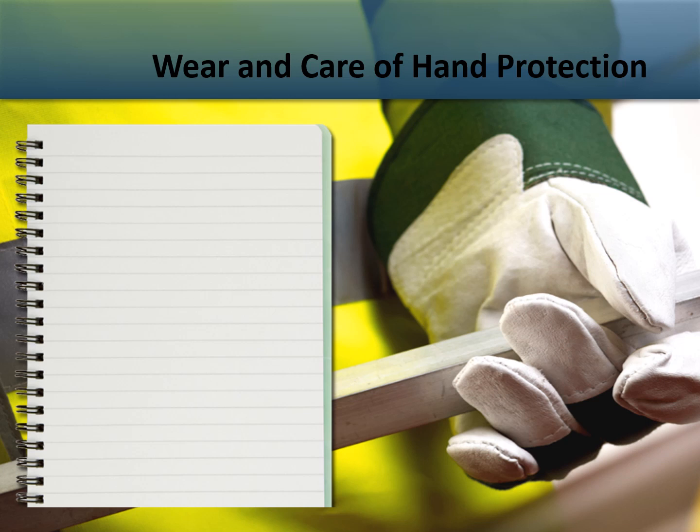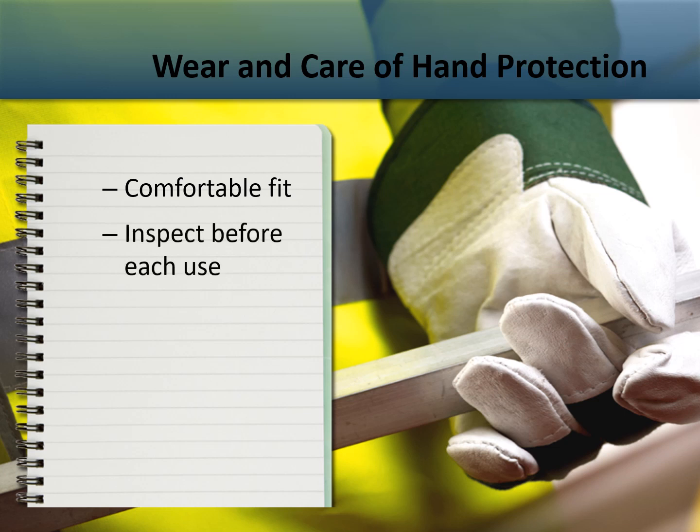As with all kinds of personal protective equipment, the proper wear and care of hand protection is extremely important. Protective gloves should fit comfortably. Gloves should not be too tight, which restricts your hand movement, or too loose, which creates the hazard of being snagged or limits the ability to grip and feel properly.